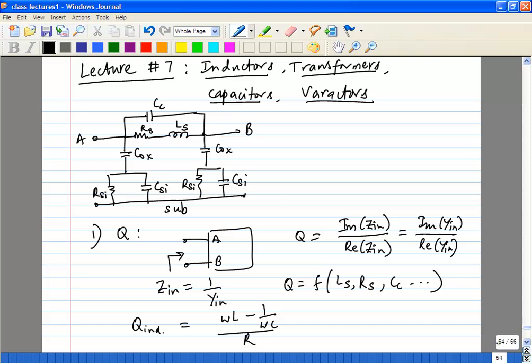So remember that it's a semiconductor, right? It has a certain ability to hold charge. It's a bulk substrate, and it has a certain ability to hold a certain amount of charge, so that you are representing it as a lumped capacitance. CSI itself will be more a function of your doping levels and so on. It will be a function obviously of the size of your inductor, because the larger you go, you are interested in the amount of substrate below your inductor. Is that clear?